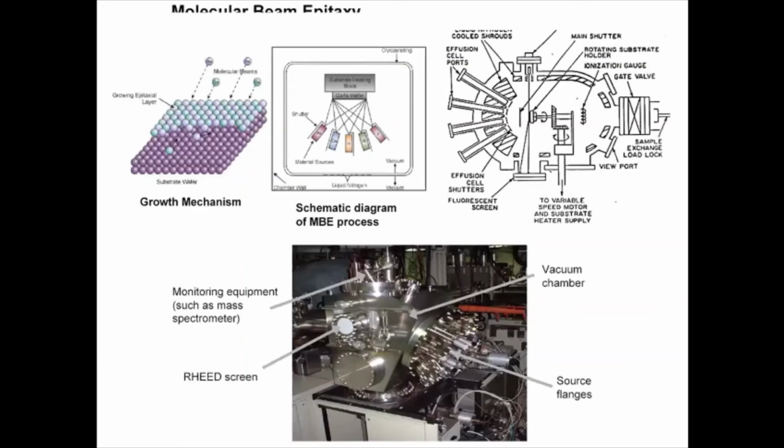And this is a typical skeleton structure of MBE. Here you have various effusion cells, and each cell contains the related elements. For example, if you want gallium, in a solid source MBE, solid gallium is stored here, and then arsenic, indium, and phosphorus. They heat it, then the indium or the gallium gets vaporized, and the vapors are focused on the substrate.